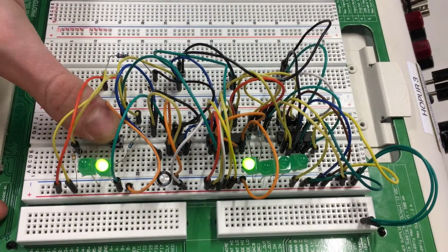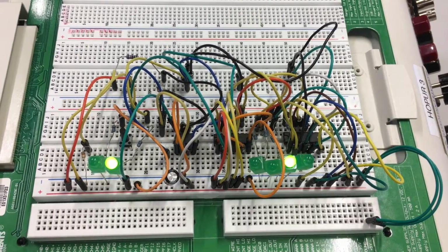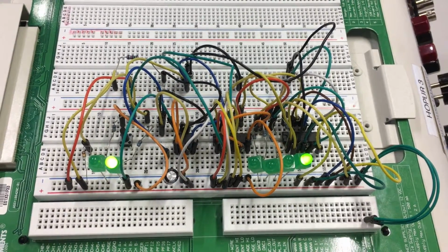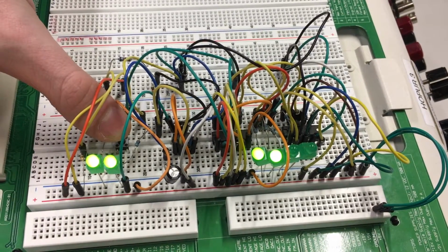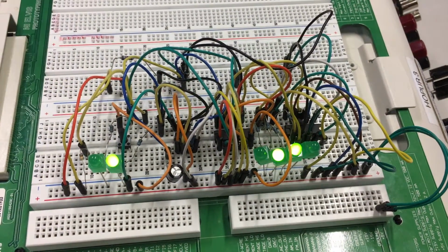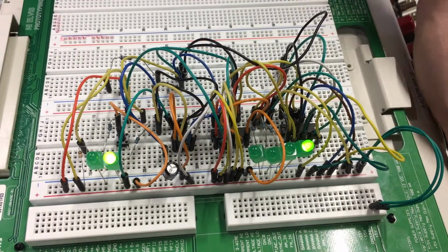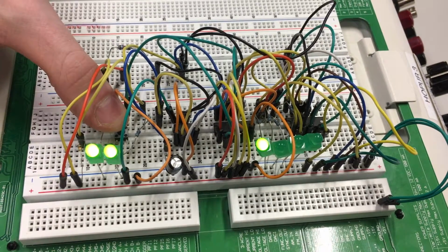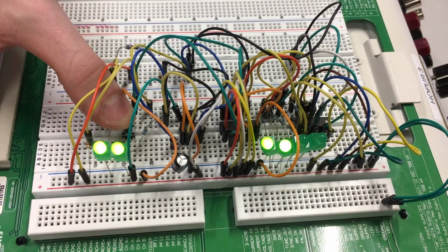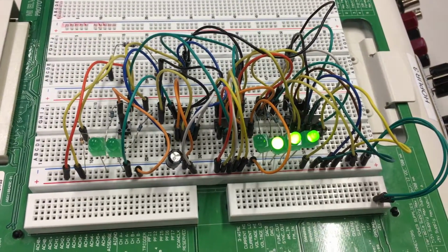In the last part, we connected the circuit to a serial connection of D flip-flops to create a shift register. We modified the 555 timer circuit, then we added 2 D flip-flops and 4 LEDs. When the button was pushed, it sent current to the first flip-flop, so the first LED was lit. Then this flip-flop sent current to the next flip-flop, so the second LED got lit, and so on to the fourth and last flip-flop.